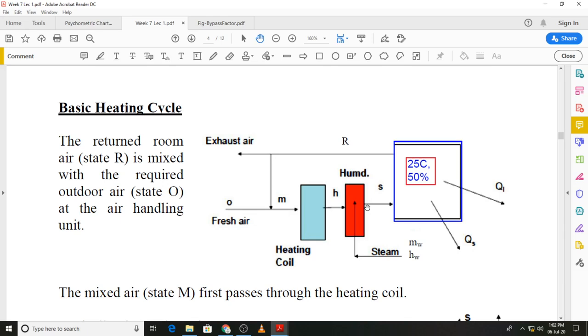in the wall. So if we keep on using the same air over time, those contaminants will build up, and that is not desirable. So we want to maintain the contamination level inside the room, or the indoor air quality, at a certain level, and to do that we exhaust part of the air which is being taken from the conditioned space and then mix outside fresh air with the recirculated air, and that is shown by this letter M over here.